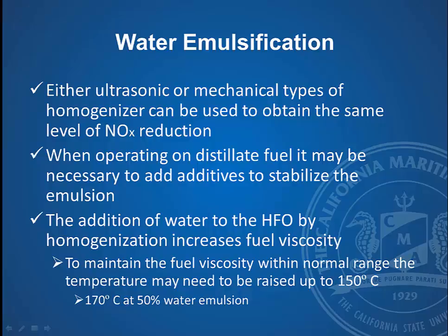The addition of water to the heavy fuel oil by homogenization increases fuel viscosity, and to maintain the fuel viscosity within normal range, the temperature may need to be raised up to 150 C, or even in some cases 170 C. This is quite hot, and that in itself is a little bit of a concern, but these types of temperatures are being successfully used aboard ships.